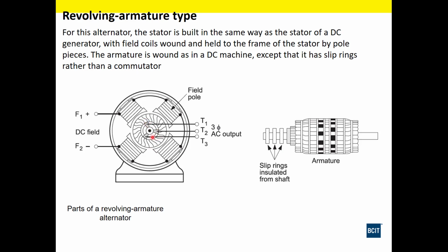There are some limitations though. If we have that 4,800 volt alternator rotating here with really high currents, we're passing all that potential and all that current through these slip rings because we have to get the electricity out of that alternator. There's going to be brushes and wear points and a lot of issues there. So it's not really a very effective design.